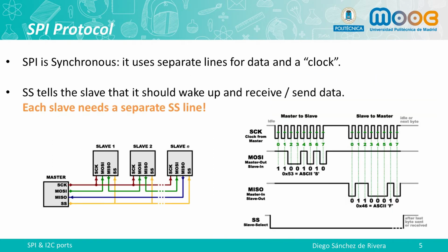It is a synchronous serial data bus. Data can travel in both directions at the same time. Data travels back and forth along the data lines between the Arduino and the SPI device. This can only happen when the slave select line is set to low. In other words, to communicate with a particular SPI device on the bus, we set the slave select line to that device to low. Then we can start communicating with it. Then set the line back to high.